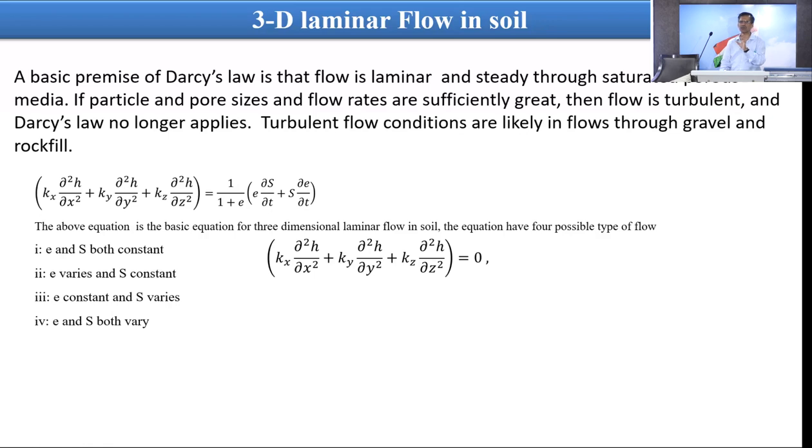So that means flow through porous media, mathematically, is one equation. This is the governing equation. There are two conditions. If it is a steady state flow, then it becomes permeability. If it is unsteady flow, that means the void ratio is changing with time, then it becomes consolidation.